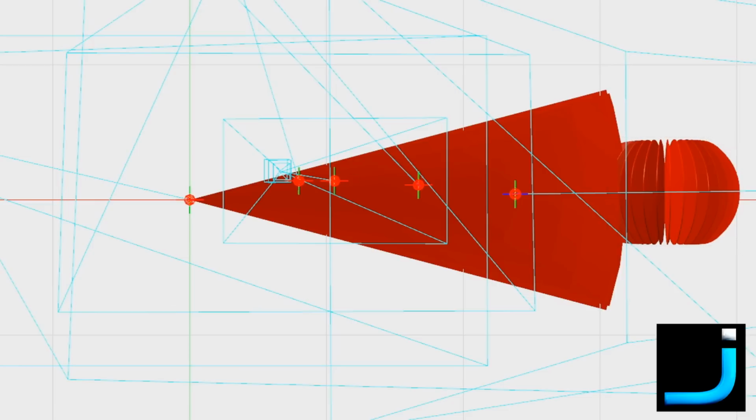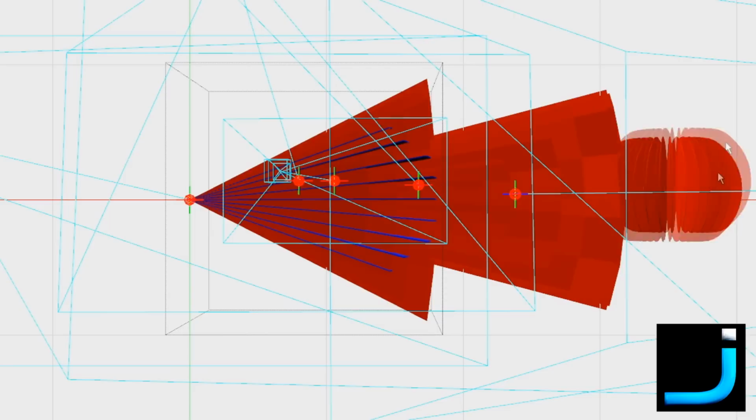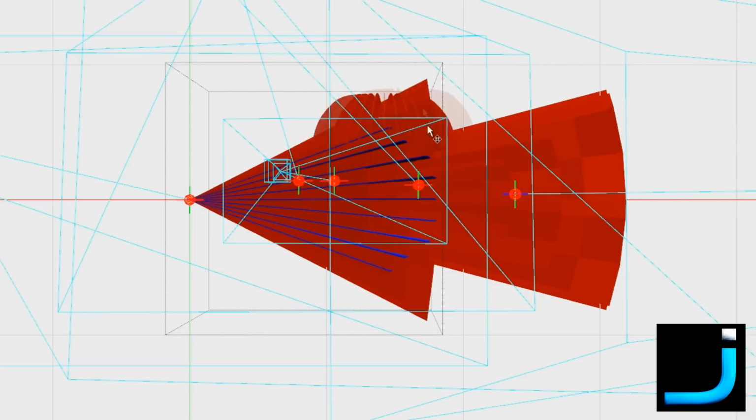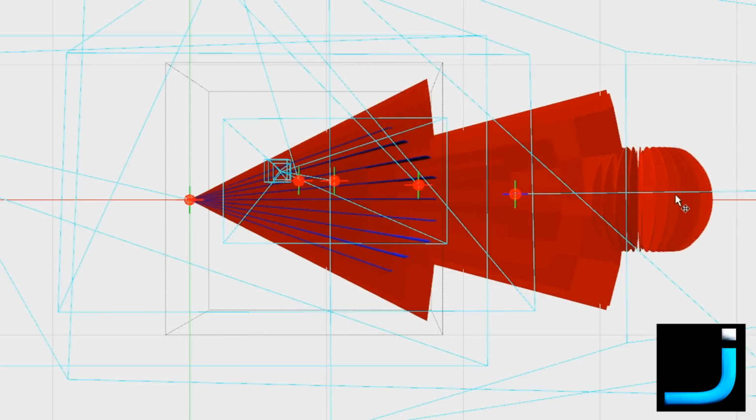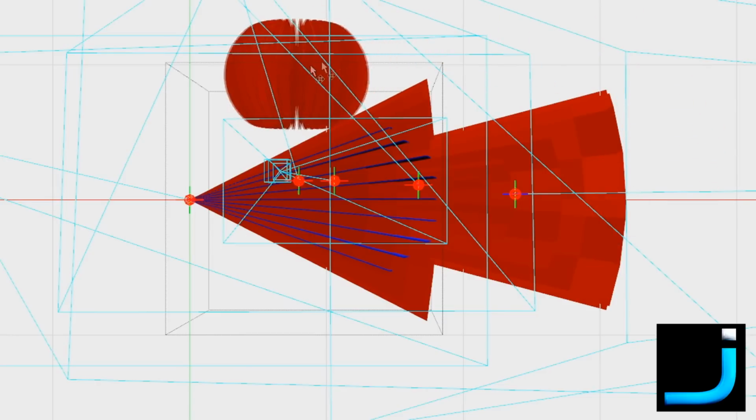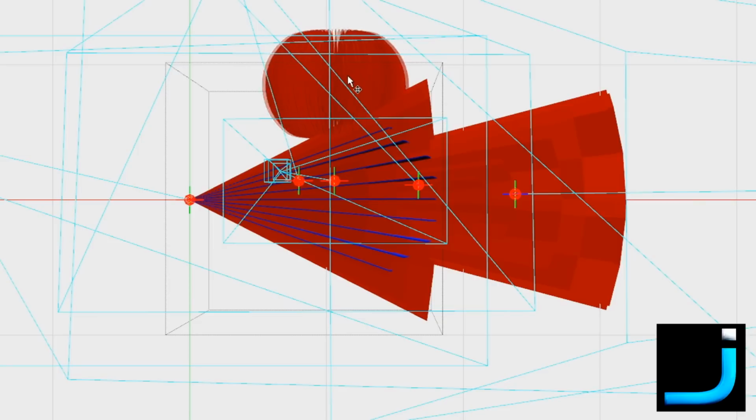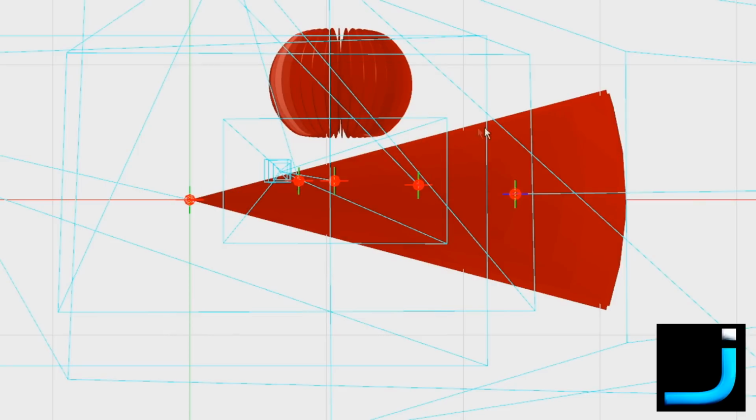Let's get the pattern on for that. It is here. So we can get to about here with your diversity, 11 decibel. We can get all the way out to here with your 15 dB Yagi. The downside, of course, is that the field of view is not quite as good. With the diversity receiver, 11 decibel, I can be flying here and get a pretty good signal. But with the Yagi, I'm out of range here, look.